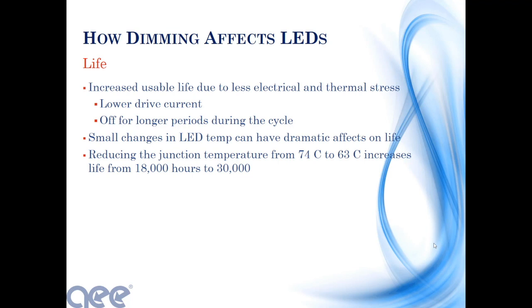The guy yesterday, in the opening session, I heard him say 100,000 hours, and I just cringed because of the projections. Nobody's run all this stuff for 100,000 hours. But that's really just talking about the life of the LED itself. We're not talking about the driver, which is where the electronics are, which is where you're going to see more of the failure modes. The life is based on lumen maintenance, and that means how much time you expect to get a certain level of light out without a certain level of degradation.